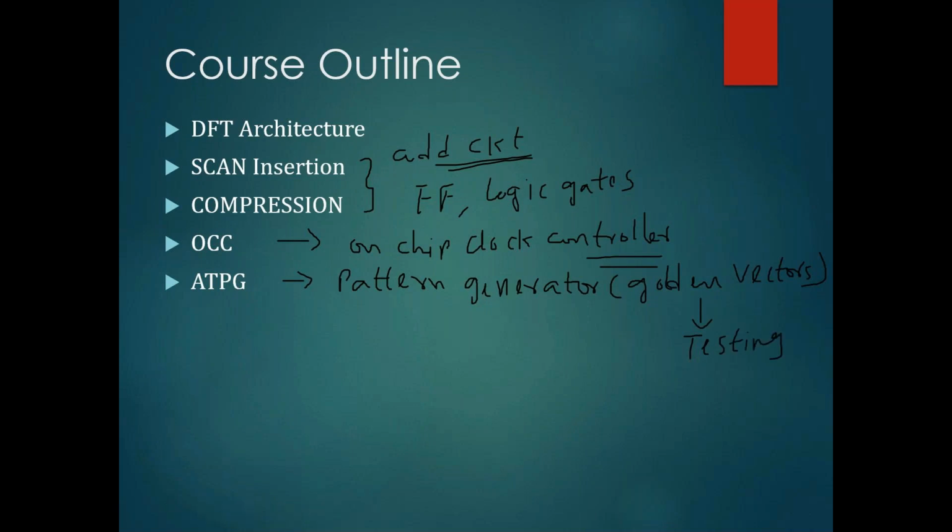So that test case also we are only going to provide. And for such multi-million gates and flip-flops, are you going to write it manually? No. We have automated tools. We have design automated tools that can help us to complete these operations. Like it can add this extra circuit, it can add this extra controller logic, it can generate these vectors for us. So we need to properly enable the operation which we want to do out of the tools we have. And finally we have to validate it and then provide it to the next team.